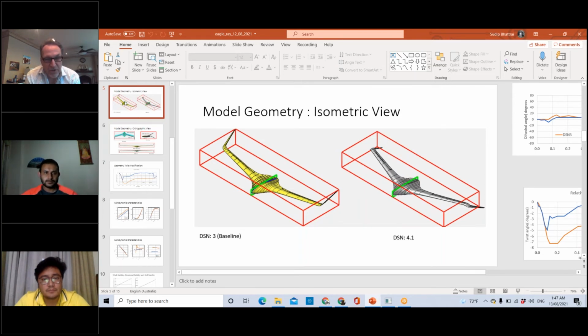So the short answer is that the winglet, at least when I first looked at the problem, was sized to get a certain level of directional stability. And it looks like you guys may have matched it. I think 0.018 or something, CN beta, between 0.01 and 0.18 is what I typically target.